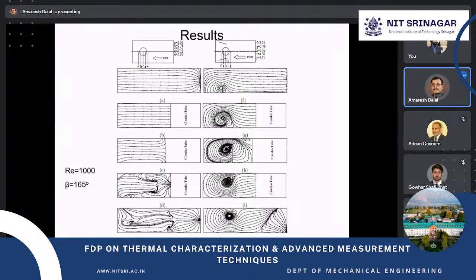Okay. So now you can see that there is no longitudinal vortex formation for the case where no winglet is there. But when the winglet is there, you can see how from the high pressure region to the suction side the vortices are generated, and they increase in strength. Because we have used a triangular winglet, as we go in the flow direction, the height of the winglet is increasing. Sorry, I'll use the laser pointer. So you can see that this is the height, and the height is increasing, and here it is maximum, and in IJ there is no winglet present.